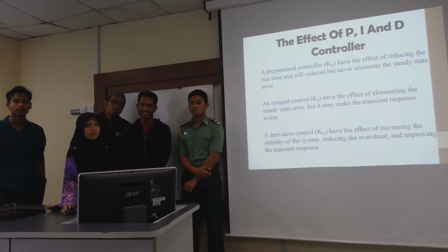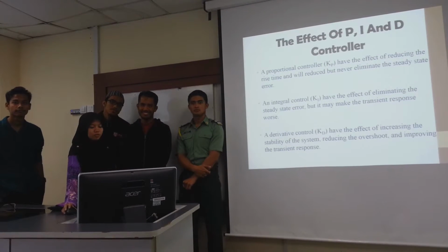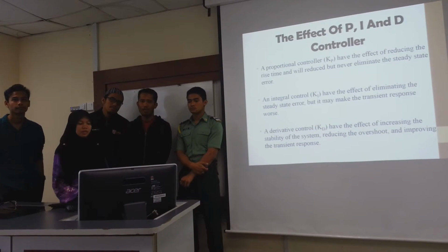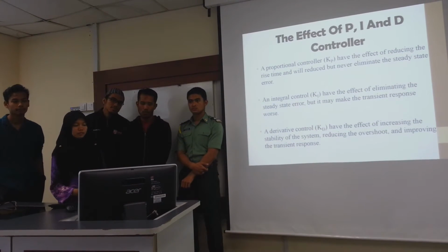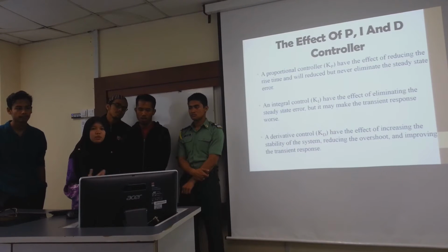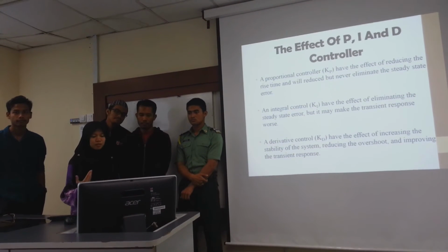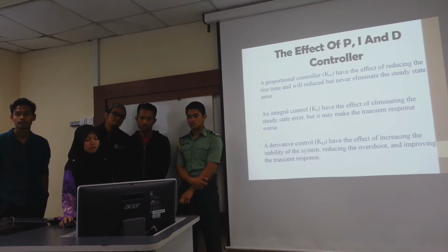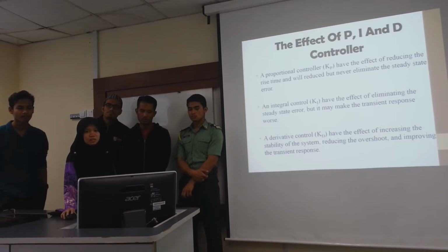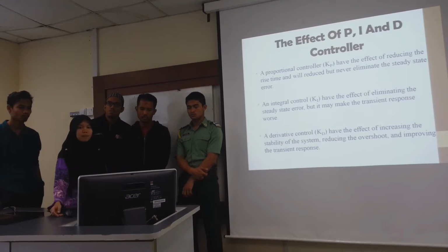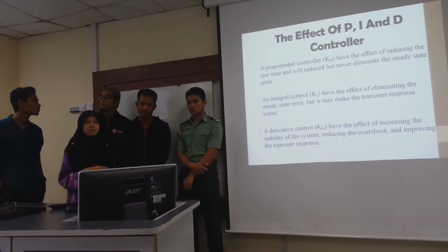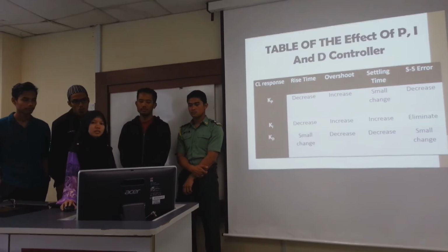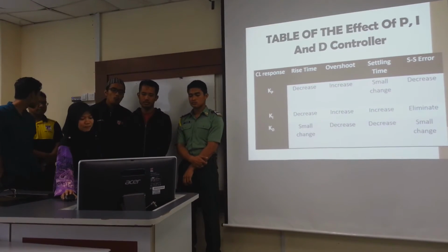The integral control will eliminate the error, but it will make the response worse. And finally, derivative control will increase the stability of the system, reduce the overshoot and improve the response. Okay, this is what I say.